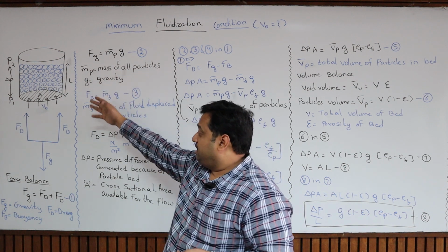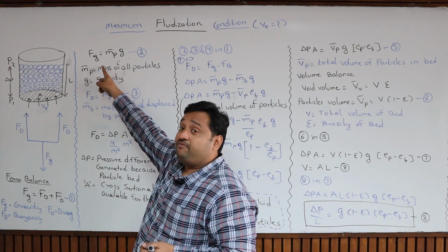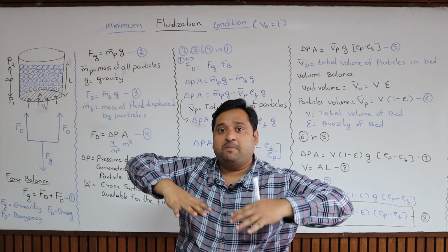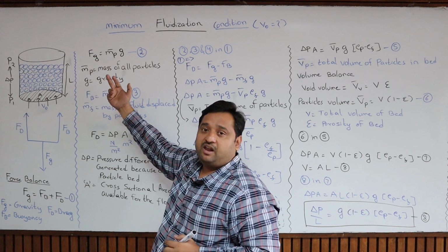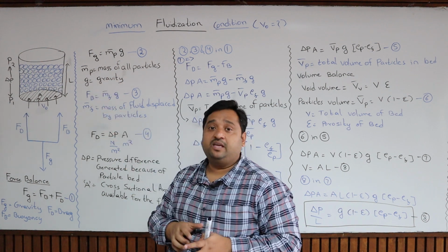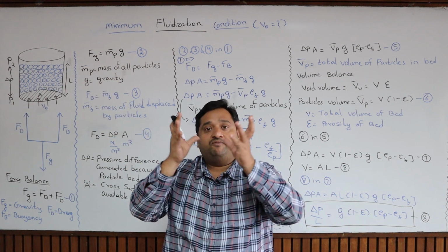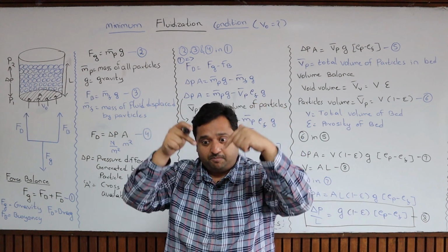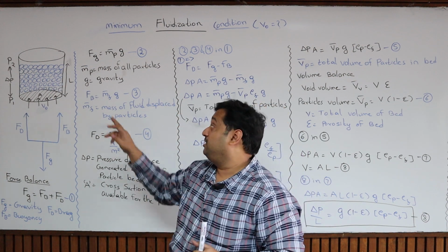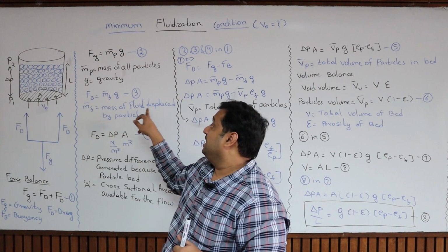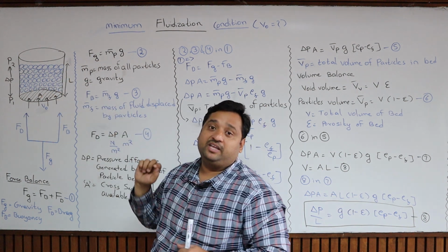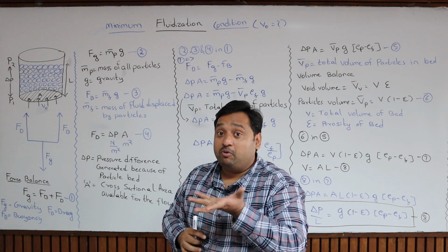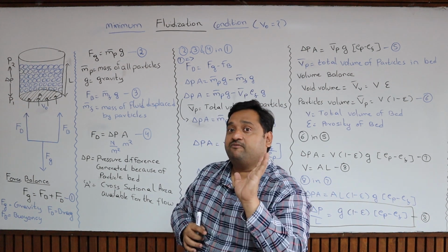From this, what is the gravity force? It is the total mass of the particles in the bed, that is m bar p into g. Buoyancy force is nothing but the force from the amount of fluid that is displaced because of the presence of the solid. That is the mass of the fluid displaced by the entire particles in the bed into gravity. That is the buoyancy that pushes from the bottom to top.